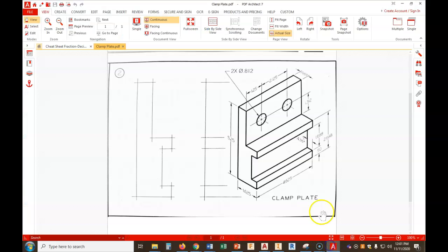Now if we go back and look at our picture, look. I can start cleaning up some stuff. This is 11/16 deep. Look here, this little upright part. So it looks kind of like a piano. Do y'all see that shape? Like an upright piano? So it's 11/16 deep. The reason why I know it, 0.688, look, 1.688, 2.688. So that's just 11/16. But that is from this edge. Do you notice this little image here? They're kind of showing you what to draw. So from here to here is 11/16.